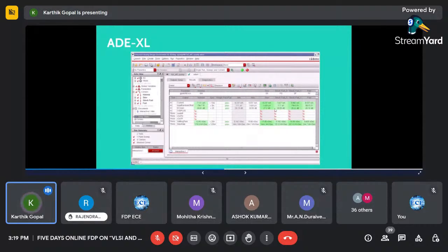If you look here, all the green colors. If you take the first line, current, nominal is there, right? That is 7.13 milliamperes. That is a typical number. But if it is slow, it is 8.23 milliamperes, and at fast, the last one is 8.037 milliamperes. So this is how we can analyze whether the chip is passing the specification at all the corners or not.